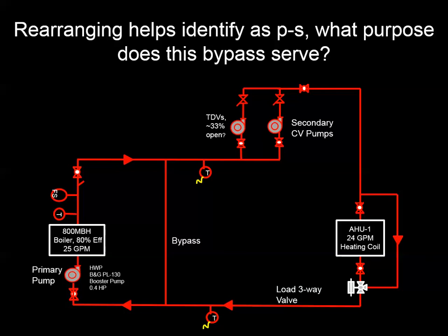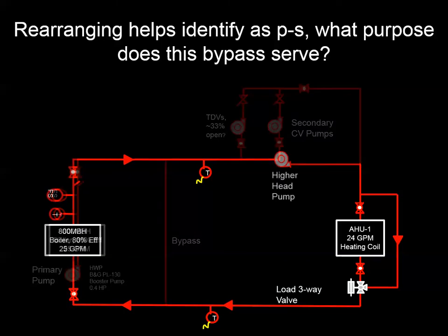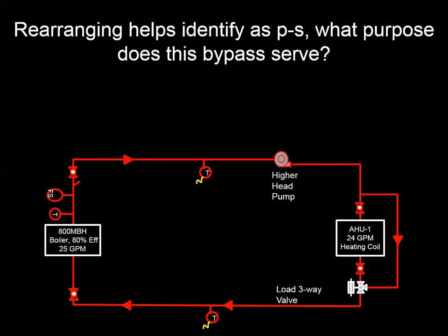So what we noticed is that in this case, because you had the same flow requirement at design conditions between the coil and the load, if there would have been a single pump or a single set of pumps sized to handle the head of the entire system, you wouldn't really need this primary secondary. And in fact, because the bypass was installed not as a short fat tube, there was actually pump interactions in this system as well.